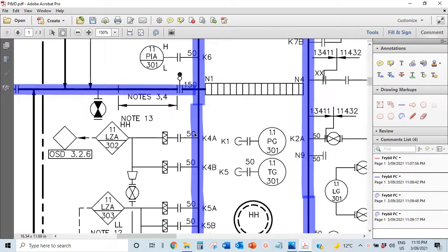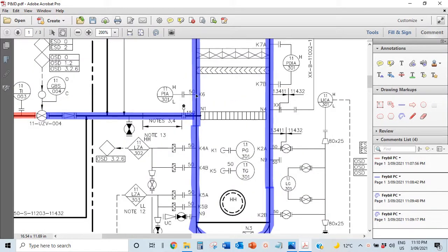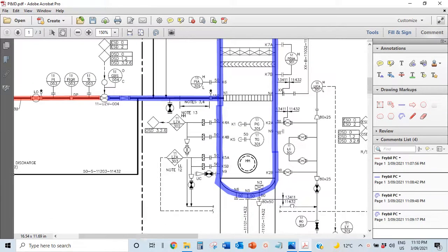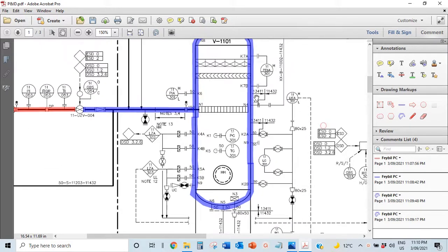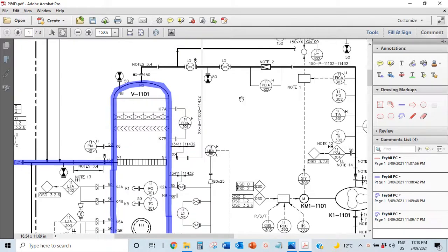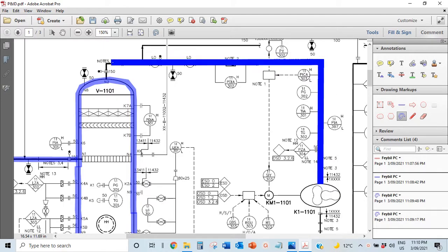So when we're doing our parts count, we're going to look at all this. All this is going to have connections to instrumentation, which are all leak sources. All the valves, they all have failure rates. We're going to pull them up and look into them. So from here, we'll continue with our isolatable section. Start from the compressor here. I'm just going to go backwards. Normally I should go forward, but this is how it flows.